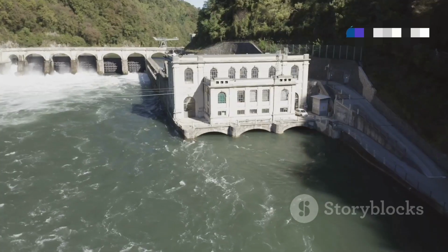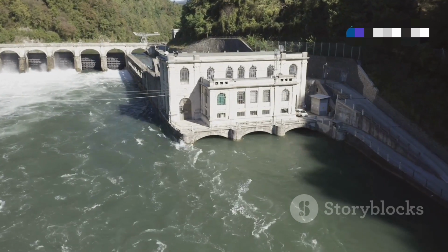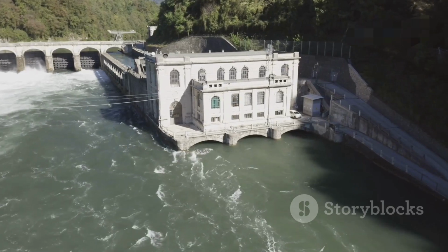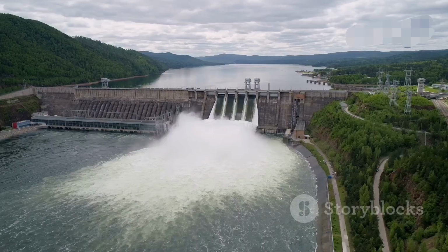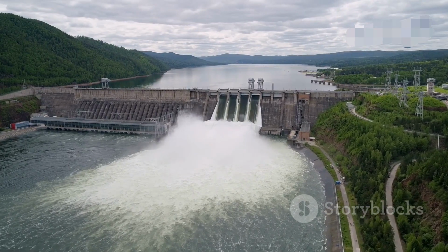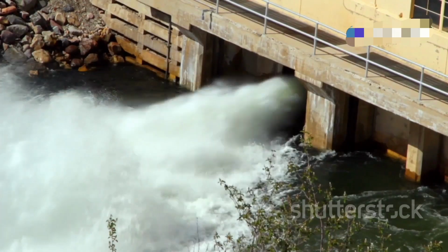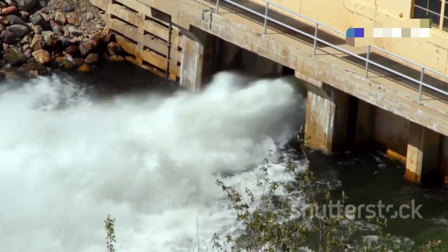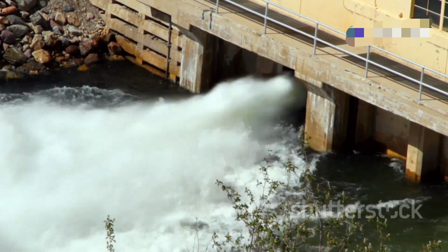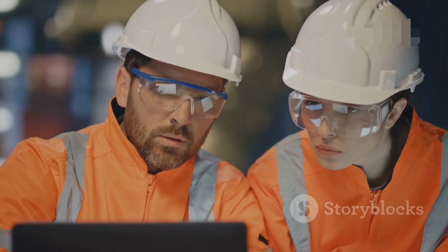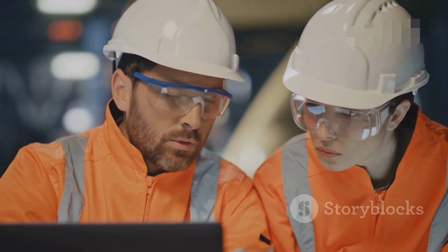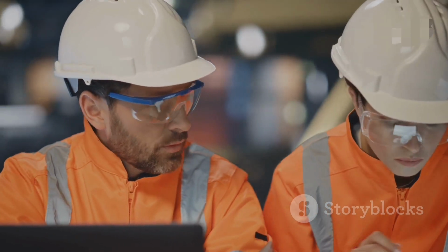be low. In contrast, a flood failure, such as an overtopping failure, occurs during extreme hydrologic conditions. The reservoir is already very full, and the downstream river is likely already experiencing high flows. These different initial conditions will significantly affect the nature and impact of the dam break flood wave. The specific breach parameters chosen for each scenario will greatly influence the resulting flood hydrograph.